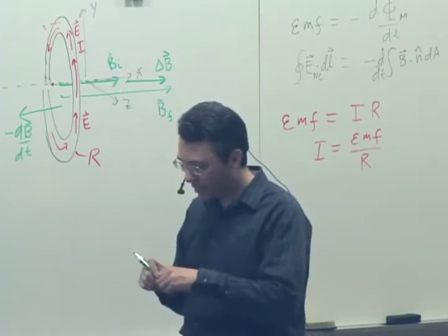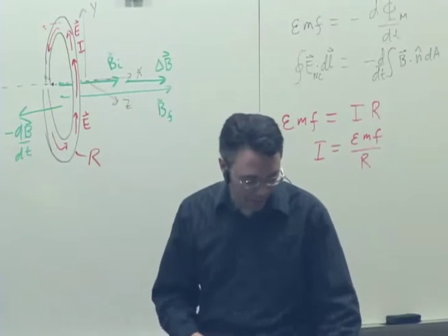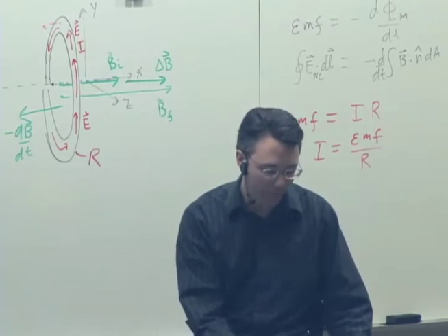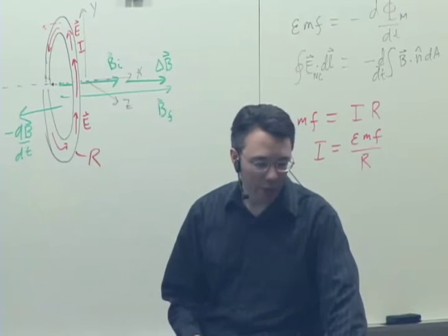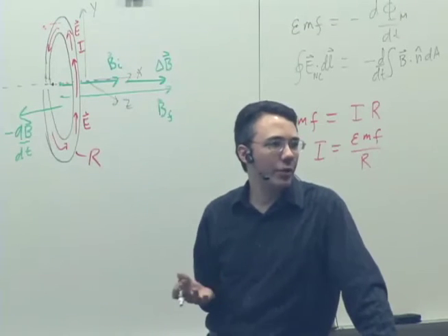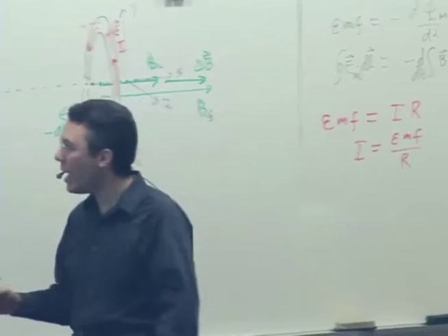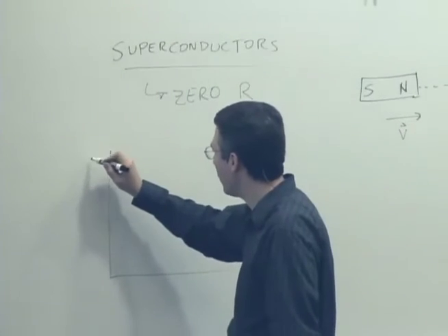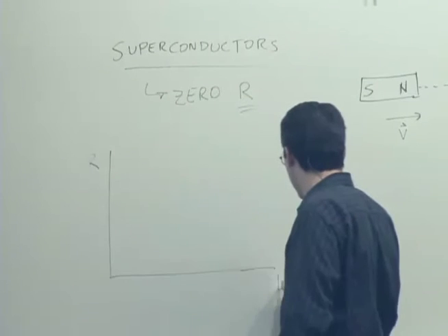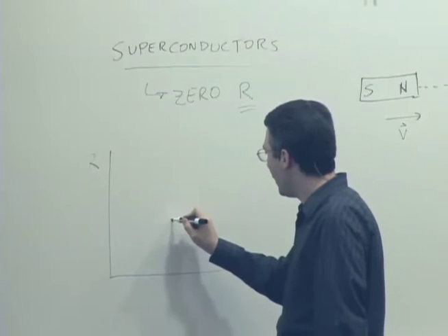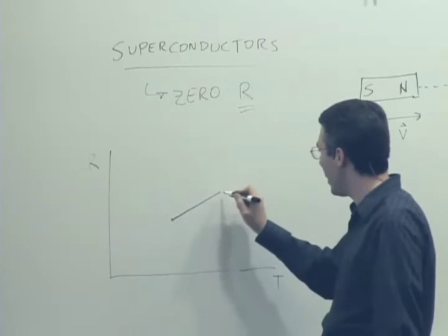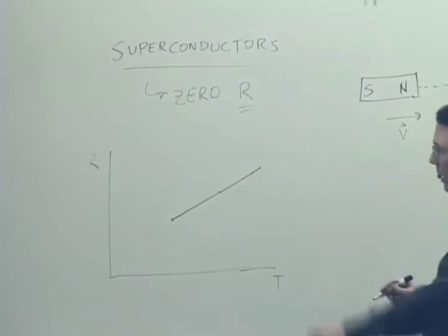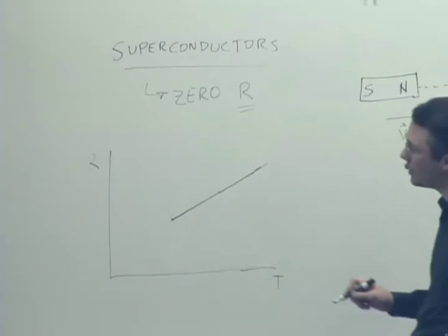And what happens is that there are particular materials which, we know that mobility, for example, changes with temperature. Okay, we've seen how if you're plotting, say, resistance versus temperature, then because the mobility is decreasing with temperature, the resistance would increase with temperature.